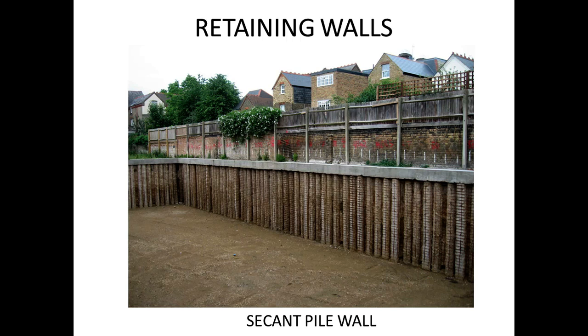This is a fairly common way, again, throughout the world. It does use reinforced concrete, and what you can see going on here is that there's a series of effectively reinforced concrete columns. So we're boring a series of holes right next to each other, pouring concrete into those holes, reinforced again, still reinforced concrete. That's the cap. So it's a series of piles. There's a concrete pile cap.